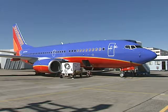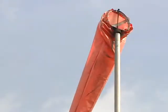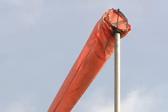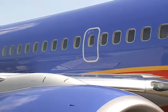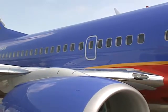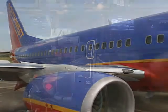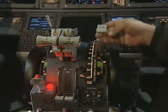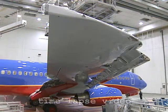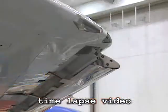Note that Boeing has no technical objection to weighing airplanes outside, as long as the wind velocity at the times the weights are recorded is within the limits considered acceptable to your regulatory authority. In all weighings, the airplane exterior should be clean and dry. Obviously, any water on the airplane will make the airplane heavier and may affect the airplane CG. Set the leading and trailing edge flaps and slats to be either fully retracted or fully extended. Boeing recommends weighing with flaps and slats fully retracted to eliminate the possibility of damage during the weighing process.